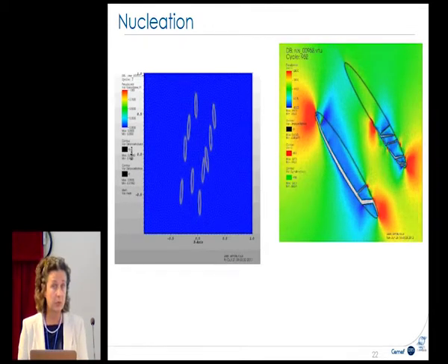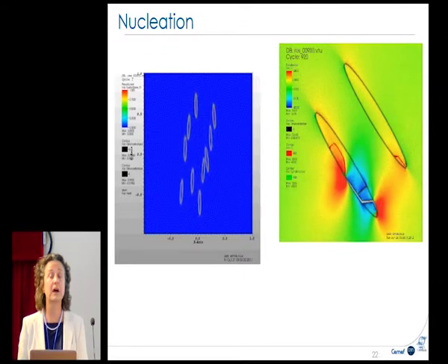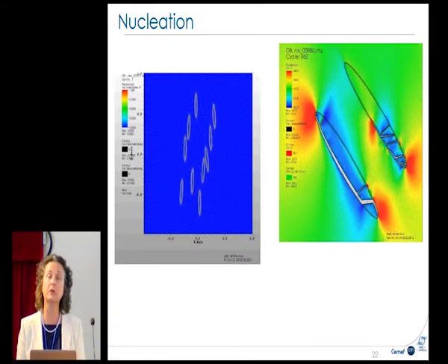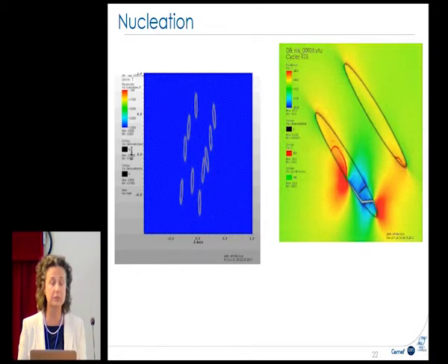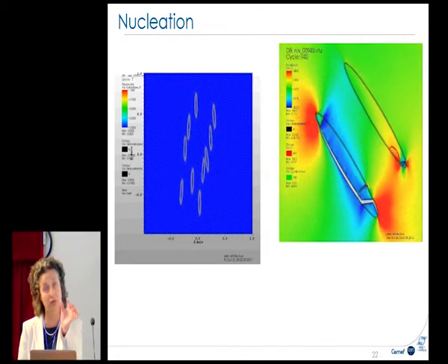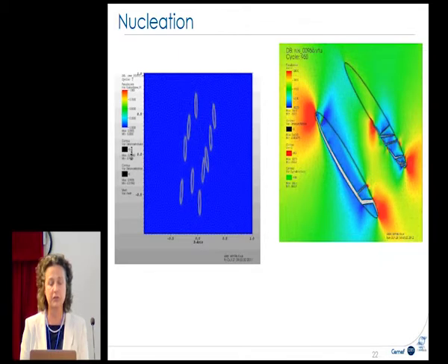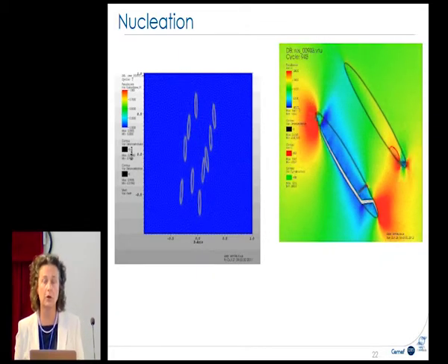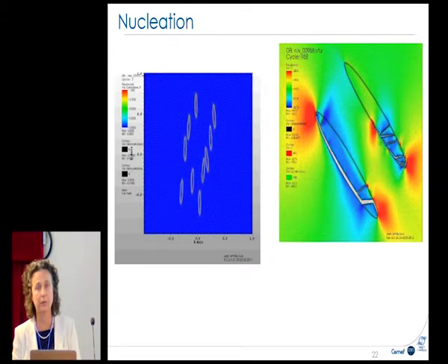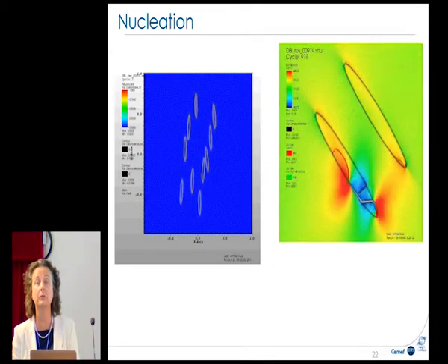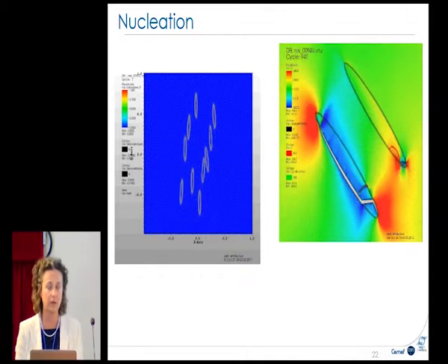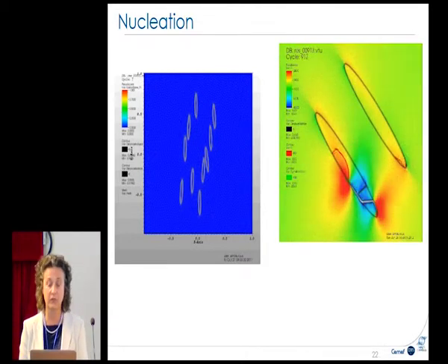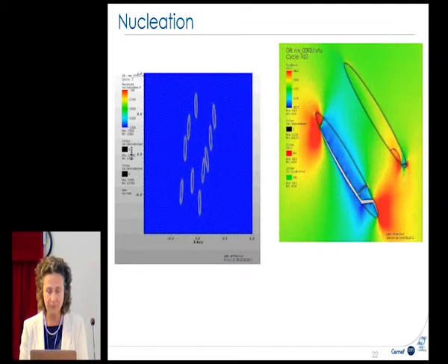Concerning the mesh around this inclusion, we can apply a very simple geometrical mesh in which we refine the interface in order to capture the geometry well. But we can also apply coupling to the a posteriori error estimator based on the mechanical values like stress, strain, and so on. So here is an example of the matrix, the void, and the inclusion.